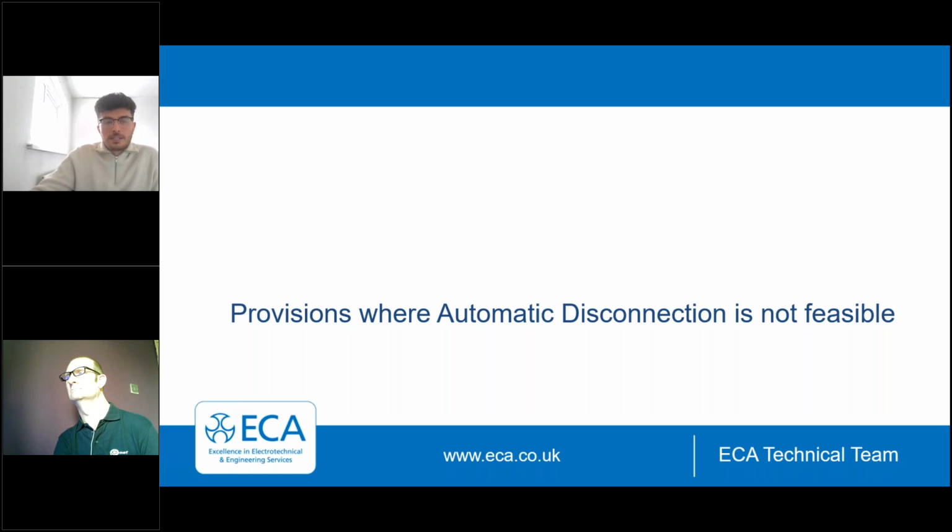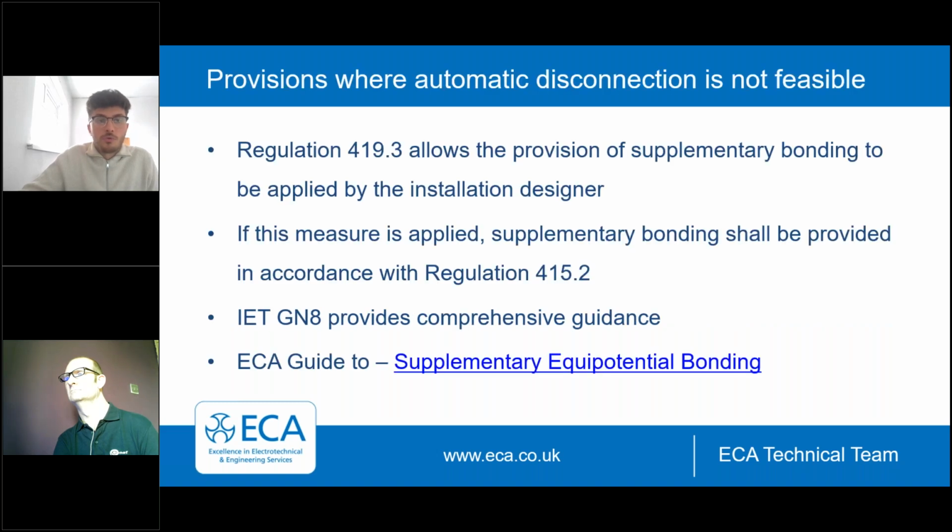Okay, and last thing to touch on now really is what about where we can't achieve automatic disconnection? This is more of an introduction to raise awareness that sometimes automatic disconnection is not feasible. Sometimes we can't achieve it with an overcurrent device, and sometimes we can't employ an RCD. So regulation 419.3 allows the provision of supplementary bonding to be applied by the installation designer. So in the cases we can't achieve ADS, we can use supplementary bonding if the designer elected to.